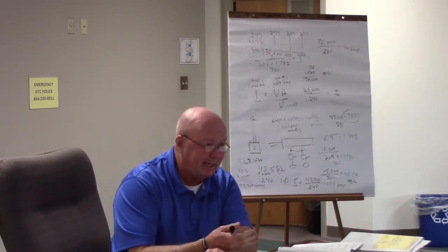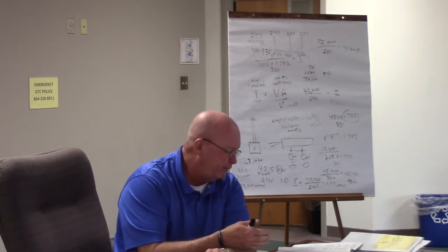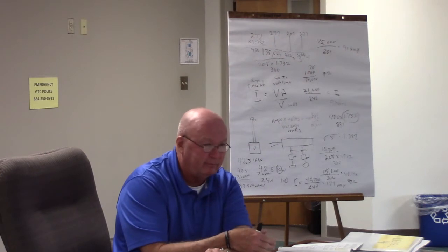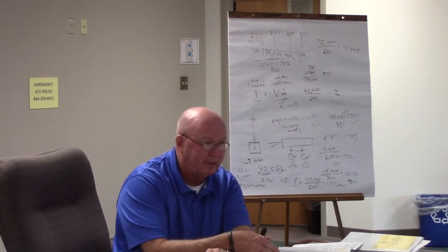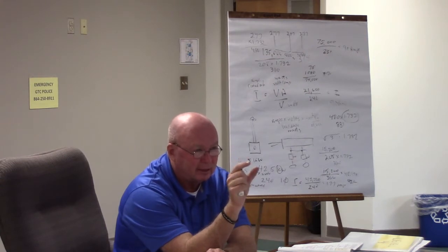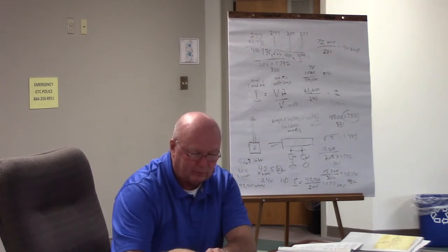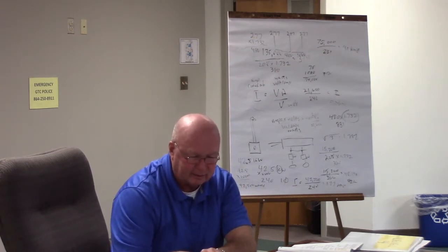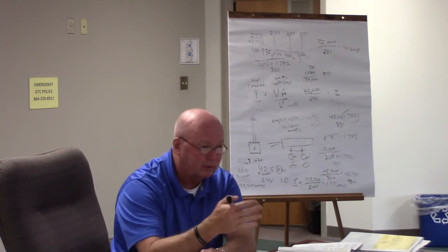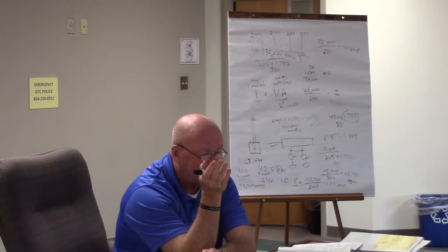But this is only a 90 amp load. But it says there in the book, if your termination is rated, and most of the time that's written on the lug, how much it's rated for. So if that termination lug is rated for 75 degrees, we already know that the wire we want to use is 75 degrees, and we're looking for something that'll hold at least how many amps? 90 amps.